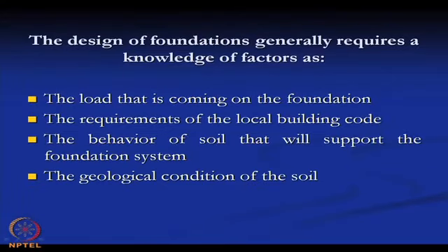Now, first we start with the fact that the design of foundations generally requires knowledge of factors such as the load that is coming on the foundation, the requirements of the local building codes, the behavior of the soil that will support the foundation system, and the geological condition of the soil. These things are very important when you design a foundation. We should know how much load is coming on the foundation.